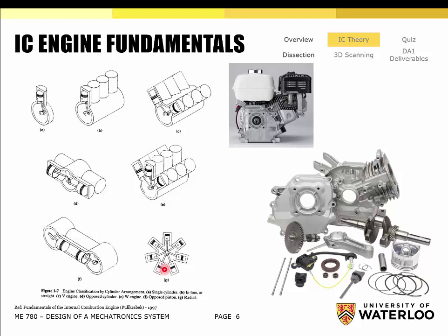So they need to rebalance all of the people and the occupants and all the gear and the luggage inside the aircraft to compensate for that. So you need to put more weight at the back of the aircraft, then you need a more powerful engine to actually lift it off the ground. So if you can make the engine compact in that direction, it has two benefits.